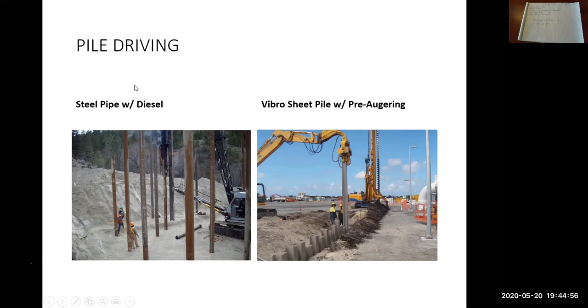Whereas on the previous slides where we looked at sheet piles and the H pile system, that's all temporary shoring. So that comes out of the ground once it's no longer needed. So if it's temporary, the contractor has to design it. If it's permanent, then the project designer, the design consultant, would design it.